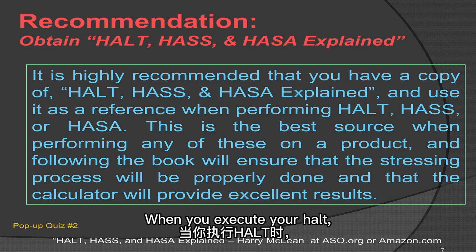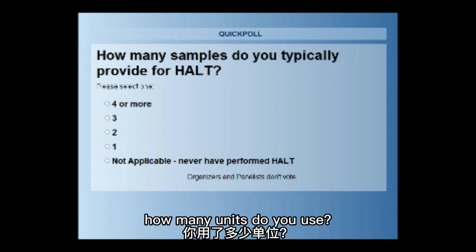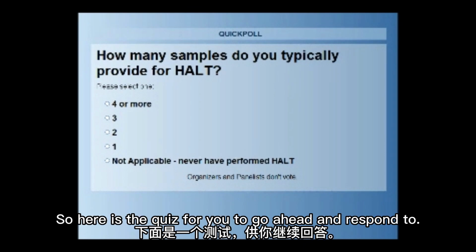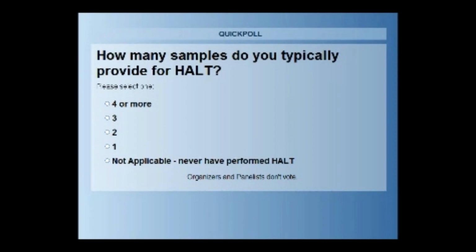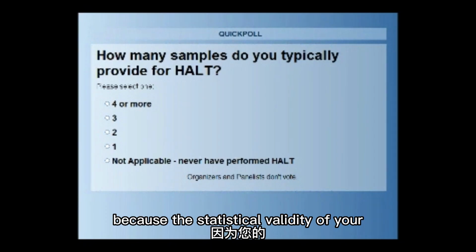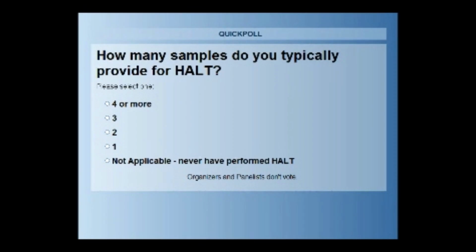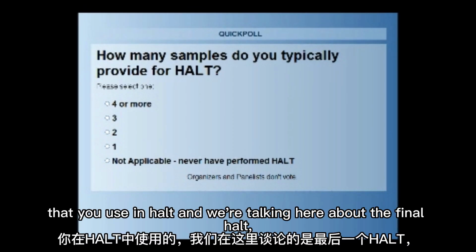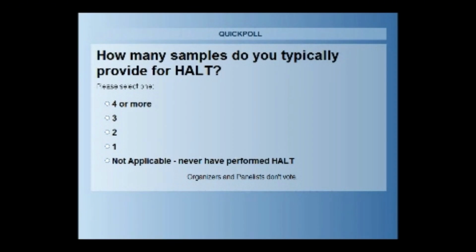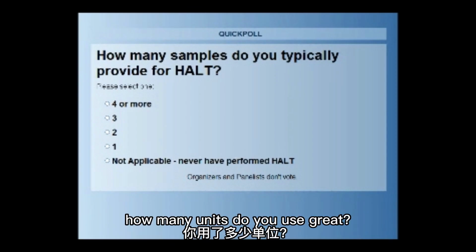When you execute your HALT, how many units do you use? So here's the quiz for you to go ahead and respond to. This is very important also later on, because the statistical validity of the output of this model is directly tied to the sample size that you use in HALT. And we're talking here about the final HALT, not the total sum of all 2 or 3 HALTs that you do during the product development, but the final HALT. How many units do you use?